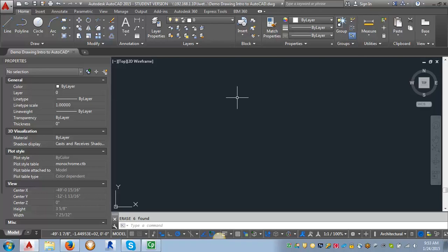So I'm going to be working in paper space size, even though I'm still in model space. That's because we're going to make this an annotative block that will scale up and down. So I want to make it true size first, and then we'll adjust the scale as we need to. I'm going to reference the AutoCAD standards to take a look at the requirements for a drawing label. And we need a circle that is 1/2 inch in diameter. So I'm going to start there.